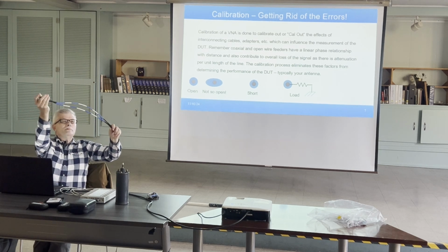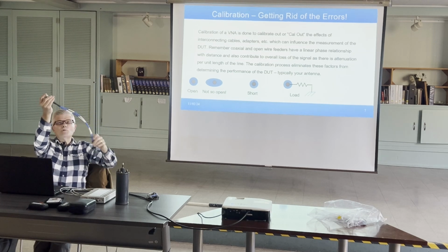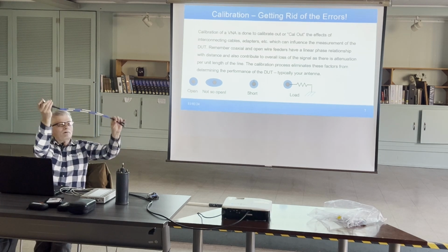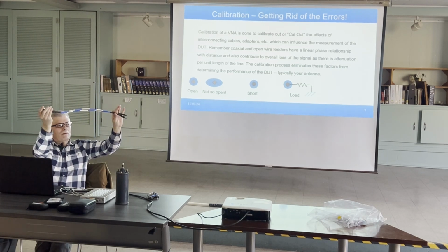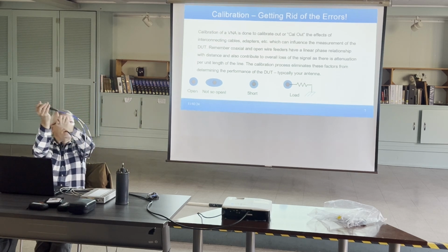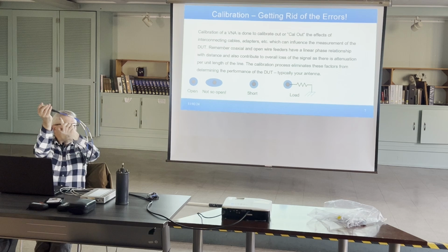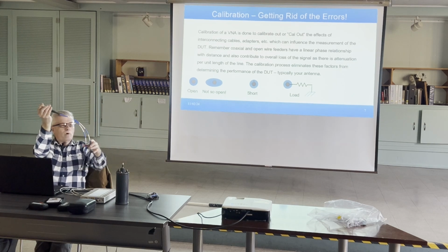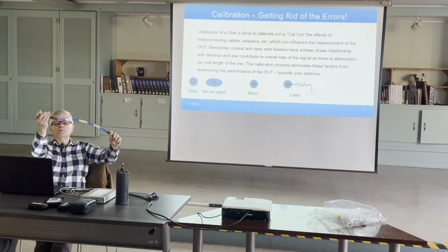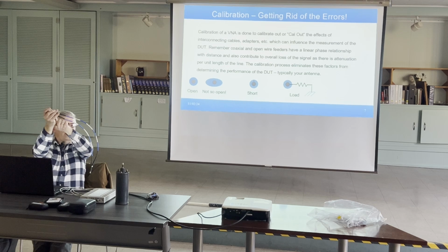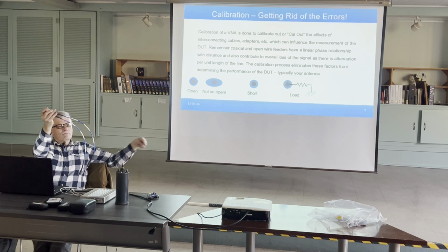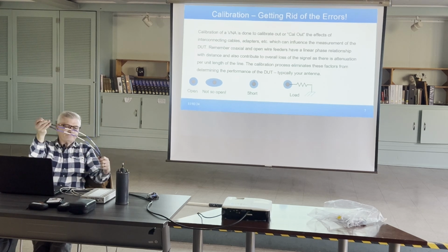Well, yes, partly true, but it's the phase shift of the cables. It's equal. Okay, the phase shift is a linear relationship. So in other words, there's so many degrees of phase shift per unit length, and it's wavelength dependent. You're absolutely right about that. So for a full wavelength, the phase rotates 360 degrees, right? Because it's traveling down the coax.